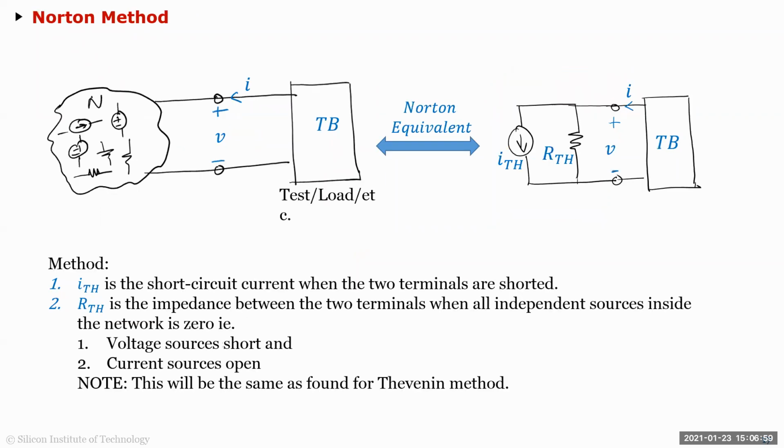And then the parallel or the reciprocal of it is the Norton, where your model is a current source with a parallel resistor, right? The current source is, obviously, you disconnect any load, you short the output and you measure the current, and whatever you measure becomes your ITH. And then the RTH is the same as before. So if you've already calculated the RTH using Thevenin, you just plug that in. Okay, so obviously they're equivalent.